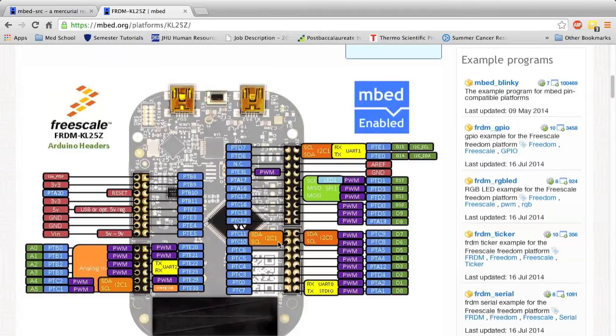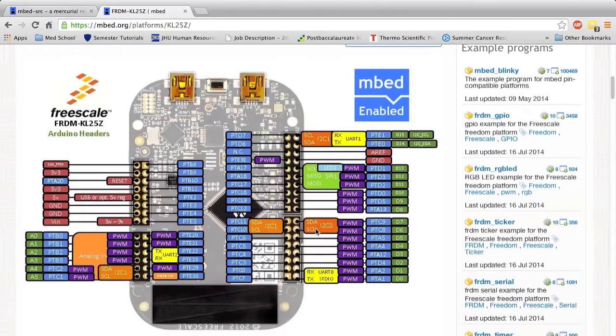It just helps to make the coding a little bit more streamlined, and it keeps things a little bit more organized. But the way that it ultimately works is that you can at most have I2C0 and I2C1 running at the same time. You cannot have two pins, each of them mapped to I2C1, running two I2C lines, because that just won't work. So in this case, you can't use PTC11 and PTC10 as an I2C line, and PTC2 and PTC1 as another I2C line, because they're both mapped to I2C1.